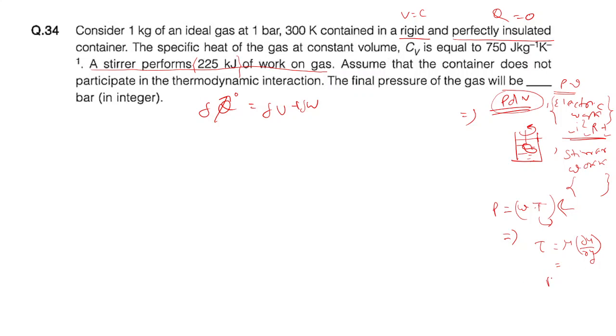So anyhow, you would be getting torque here, sir, and one thing I have to ask you. Which one are you telling, that multiplication with area? The shear stress you would be getting by this equation. Oh yeah, shear stress. Got it. Shear stress tau multiplied with area gives the force, and force multiplied by where it is acting gives the torque. Multiply by how much rotation you are giving, and that way you get the power.